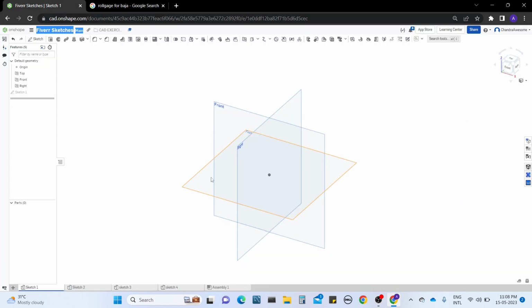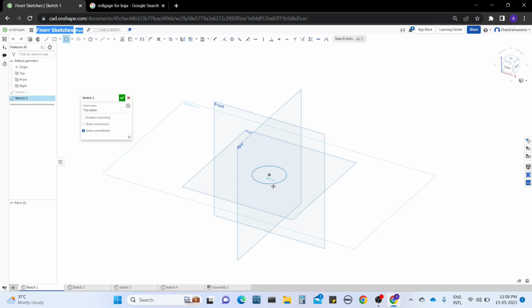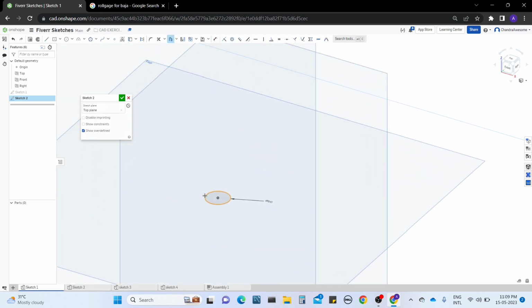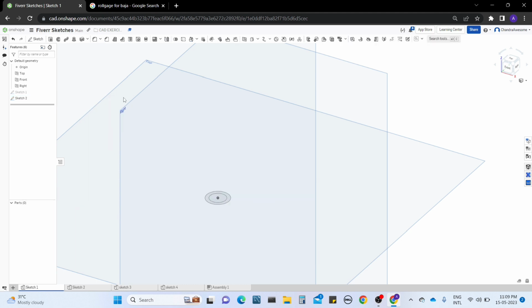So just come in here and create a new sketch of a pipe with the required dimensions as you want. I'm going to give about 100, right? So it should be 10, at least 10 mm. Then do the offset operation and give the inside radius, let's give 1.5 mm, and click OK. Now we have created the second sketch.